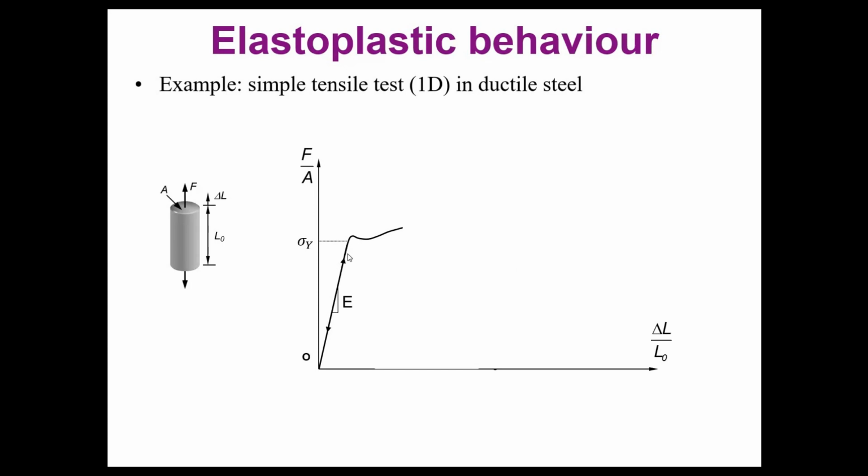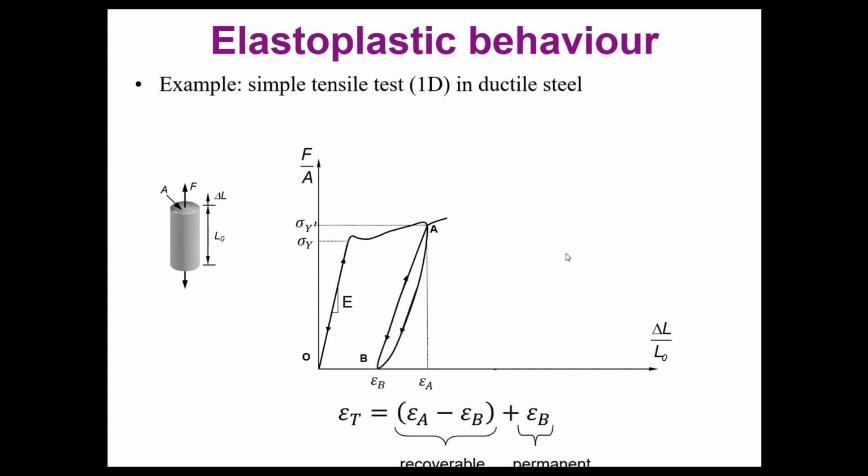So we abandon the linear elastic isotropic behavior that allowed us to load and unload and recover all the deformations, and we now have deformations that are not linear anymore, and actually not elastic anymore, because at some stage we unload the structure and the material. What we are going to have is this behavior, as we saw before.